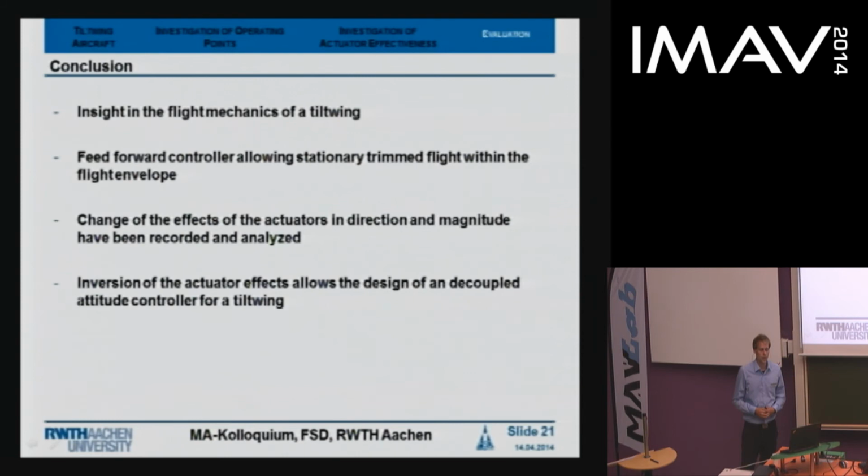And for pure aerodynamic flight, we also proved the concept in free flight higher than 10 meters per second, as I just presented. The change of the effects of the actuators in direction and magnitude have been recorded and analyzed. And an inversion of these effects helped to design an attitude controller that is pretty much decoupled in rolling and yawing. And we proved this yesterday at the flight competition. Thank you very much.